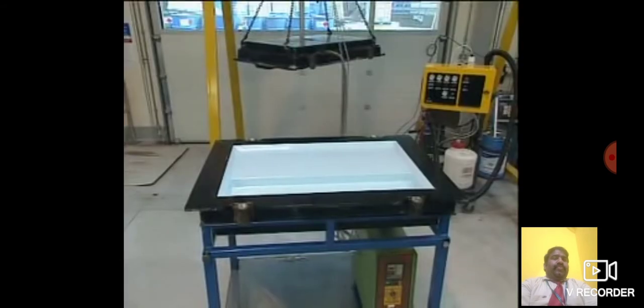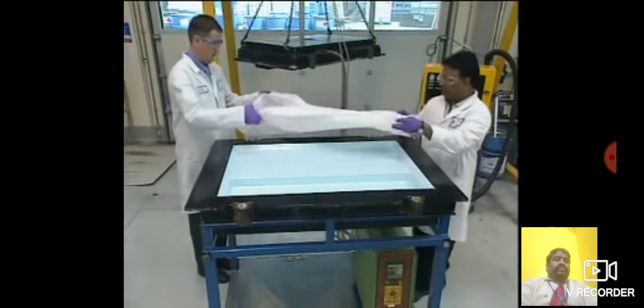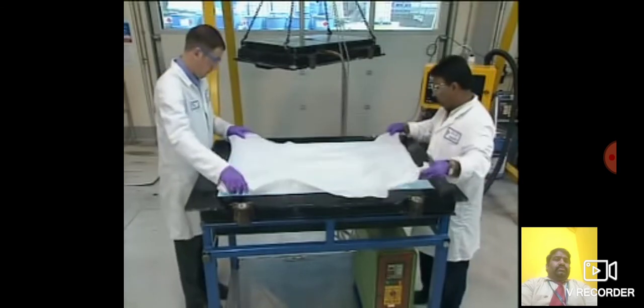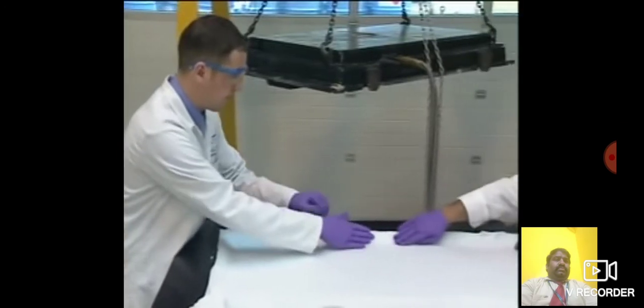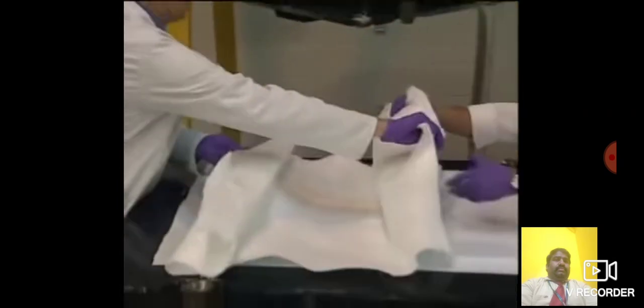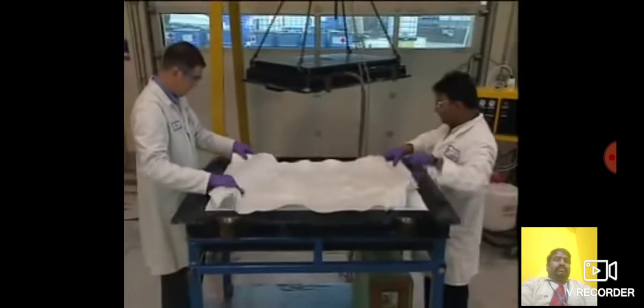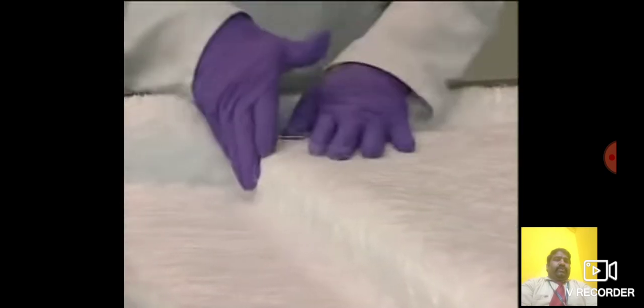The mold is gel-coated by either hand or spray application. Because of the use of heated tooling, the reinforcement can be laid onto the gel coat far quicker than at ambient temperatures. A surfacing veil or fleece material, as shown here, can be used to reduce the glass print-through. Once again, deformable stitched mats, such as Rovicor, offer distinct advantages in glass loading. Core materials may be incorporated, but their dimensional accuracy is critical to the success of RTM.